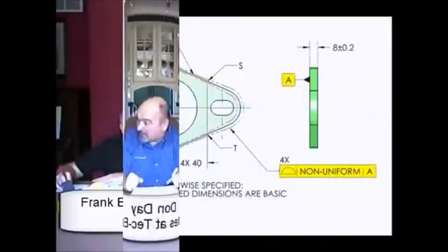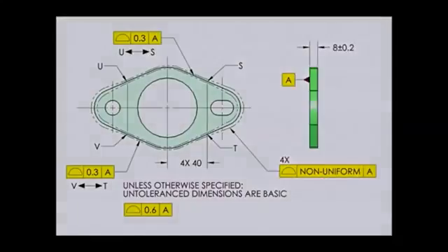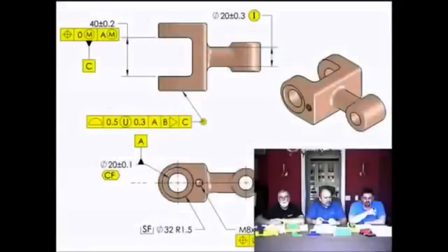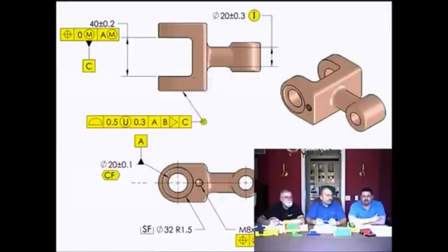Well, I guess looking back at it, the profile controls are kind of a big thing for me. They really expanded the surface profile section. The addition of non-uniform zones to smooth transitions between profile control zones is important. It's a new way of documenting it. They've included an all-over symbol where we used to have all around to control the profile around contiguous geometries. Now we have an all-over symbol. It supports general surface profile tolerancing, which has been a real big issue for moving towards solid-based design and manufacturing. So it's a big step forward in that way.